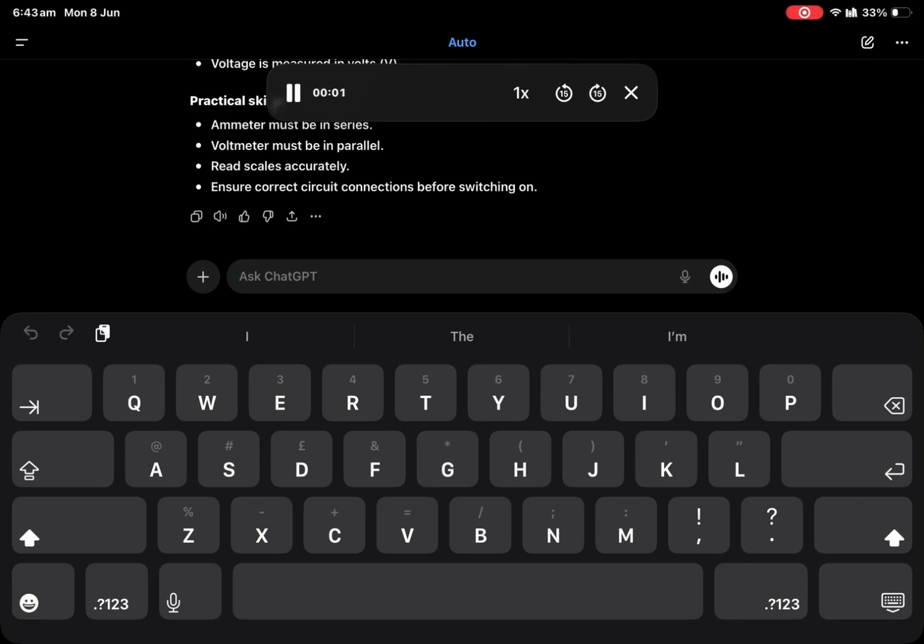For using electrical circuits to measure the voltage and current passing through a wire, 3.1.8, know this method. 1. Set up a simple circuit with a power supply, wire, ammeter, and switch in series. 2. Place the ammeter in series to measure the current through the wire. 3. Connect a voltmeter in parallel across the wire to measure the potential difference, voltage. 4. Switch on the circuit and record the readings from both meters. 5. Change the length or type of wire if required, and repeat the measurements.